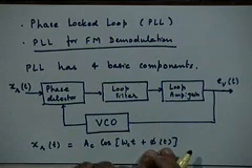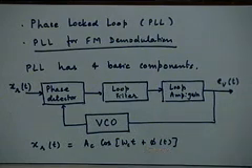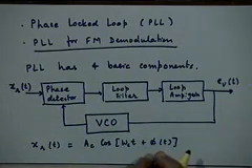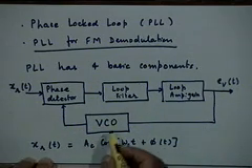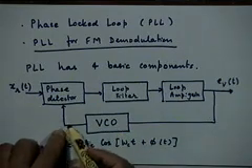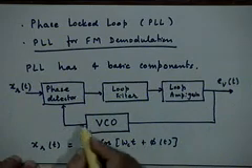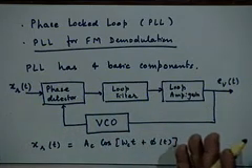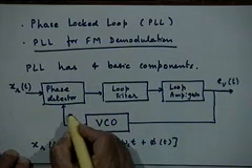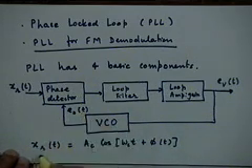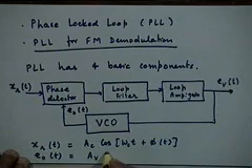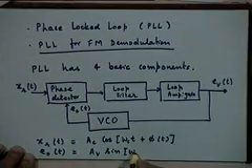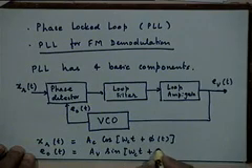It contains your message signal in terms of the fact that phi of t will depend on m of t, right. It will be proportional to integral of m of t, any FM signal. Your VCO here in this loop will produce some other signal of similar kind, right. We do not know what it will be exactly. So, let us say this VCO signal, let us call it e sub o of t, that will be some A sub v sine of omega c t plus theta of t,